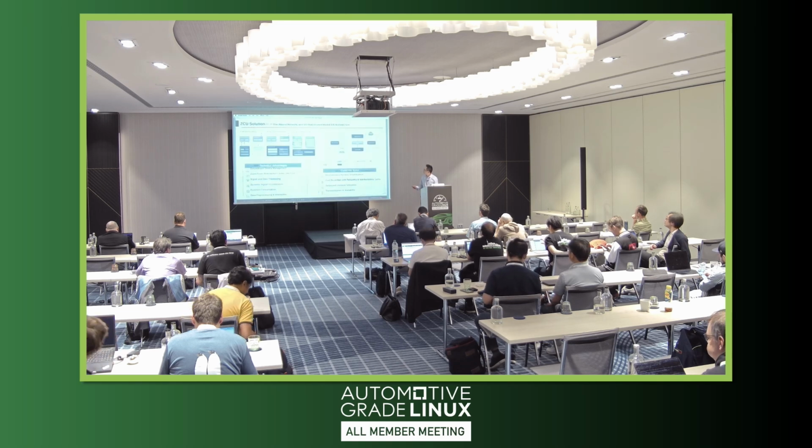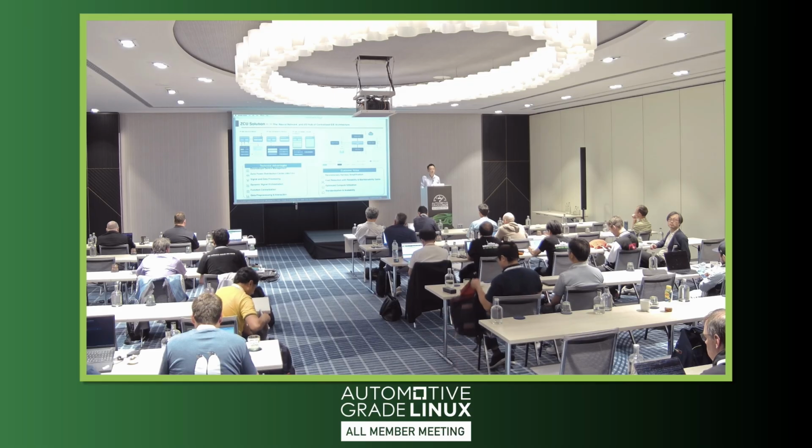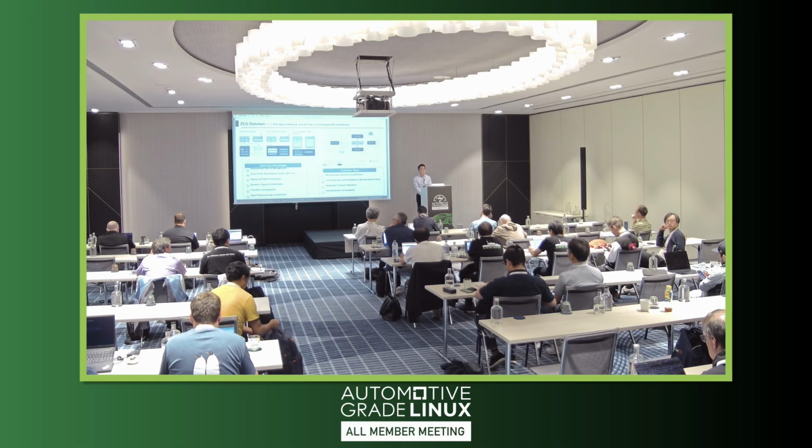I mean physical side collisions, and it would be very difficult for us to place those kind of zonal controllers on the left and right hand side. And it also makes the system fail recovery, fail-safe type of executions much more complex than the central architecture. So how can you manage those kind of things?